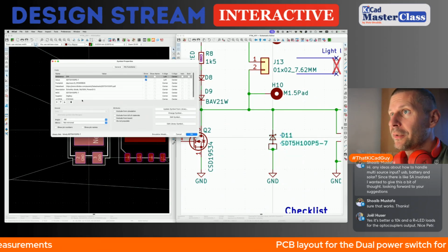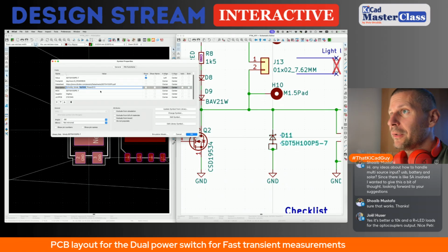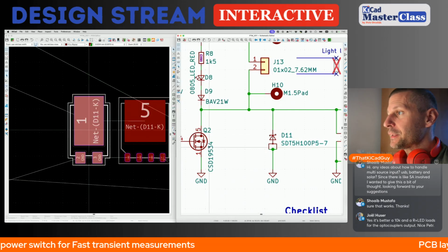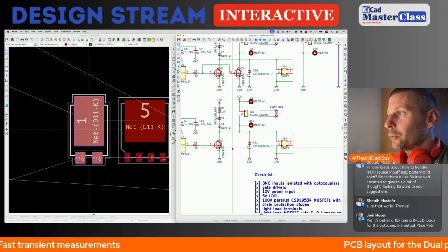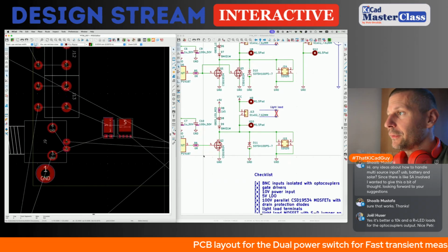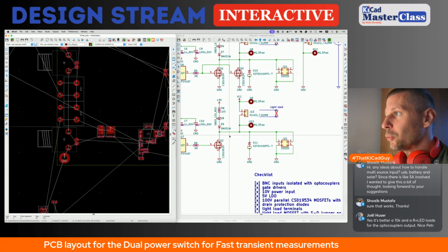I chose the 100 volt 5A diode in a rather big package. The subtle substrate diode wouldn't be enough to protect the drain from overvoltage when switching inductive loads.